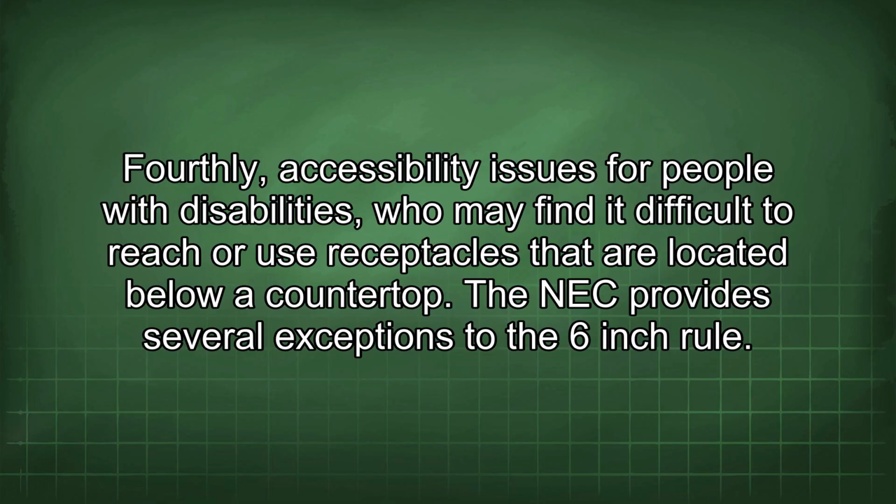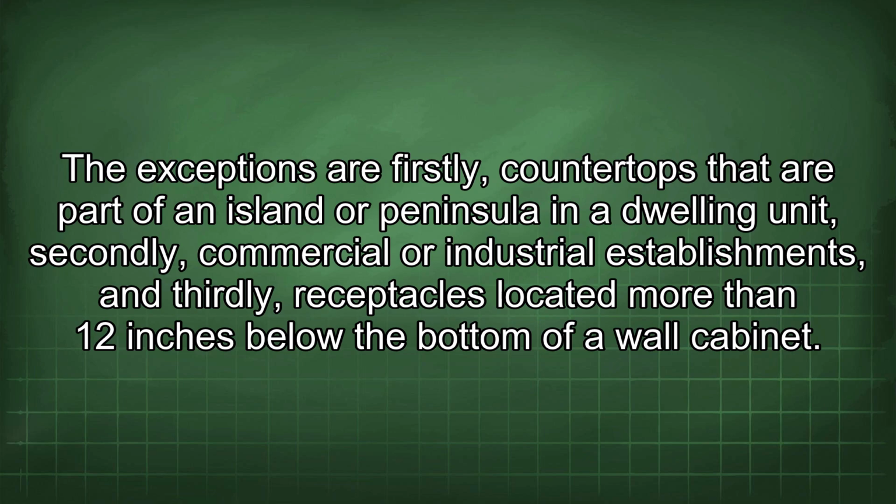The NEC provides several exceptions to the 6-inch rule. The exceptions are, firstly, countertops that are part of an island or peninsula in a dwelling unit, secondly, commercial or industrial establishments, and thirdly, receptacles located more than 12 inches below the bottom of a wall cabinet.